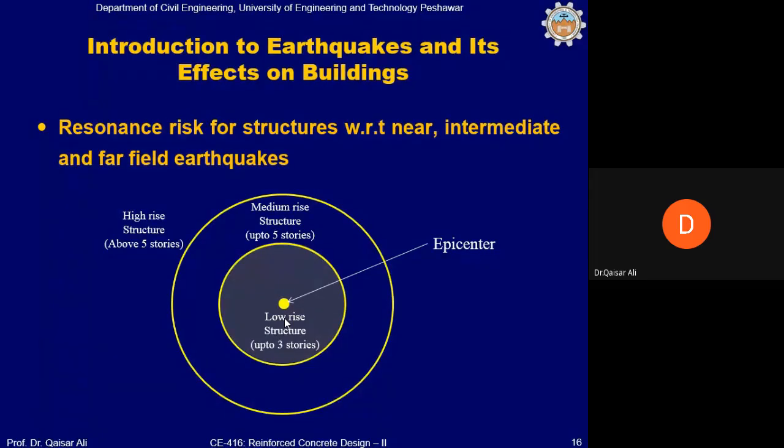This depends on the energy imparted by the soldiers' steps and the resistance offered by the bridge, that is, on the capacity of the bridge reaching its limit. So resonance with a small energy may not be dangerous. Resonance with enough energy, greater than the resistance capacity of the bridge or object, may create problems.